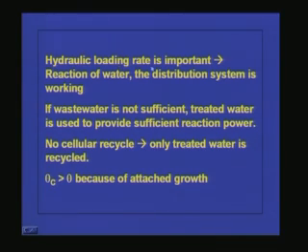The hydraulic loading rate is important, because based upon that one, the distribution system is working. If wastewater is not sufficient, treated water is used to provide sufficient wetting, and no cellular recycle is required, only treated water is recycled. Theta C is always greater than theta. Theta is the hydraulic retention time. Because of attached growth, whatever is the biomass generated in the system, most of it is staying in the system itself. So biological sludge retention time in an attached growth system is always much higher than the hydraulic retention time.